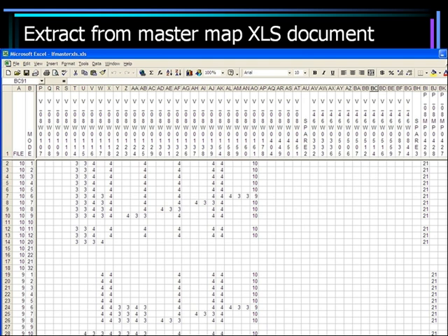I would say that. The products in these tanks haven't changed probably for 3 or 4 months, and the valving probably hasn't changed. It's all new valves. You don't change this map for products. You only change this map if a valve changes or is added, or you put a limit switch on a manual valve. That's when you'll change it.